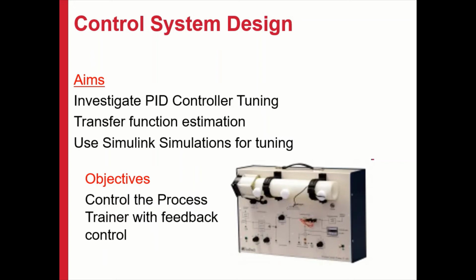So welcome to our control system design laboratory, and the aims of the experiment are to investigate PID controller tuning, to have a go at working out a transfer function for a real system, and then using that transfer function and Simulink, a simulation package, to tune up the PID controller in simulation and then compare the simulation results with the real results that we've got from our PID controller tuning.